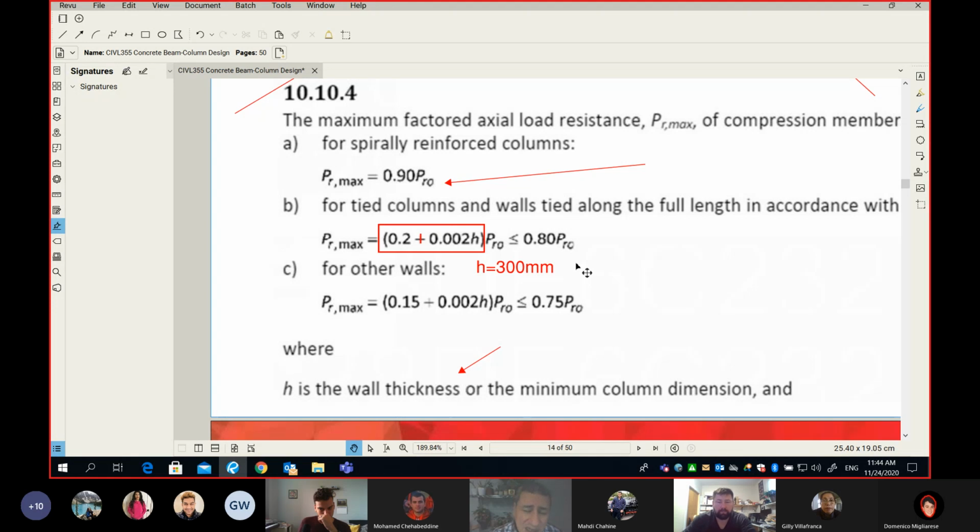Guys, why do we say minimum 200 in the beam? We have cover and cover, we have tie and tie, we have 2 bars, and we have a spacing. All of that needs spacing, right? And I can tell you same thing here. Practically, I would tell you minimum 250.